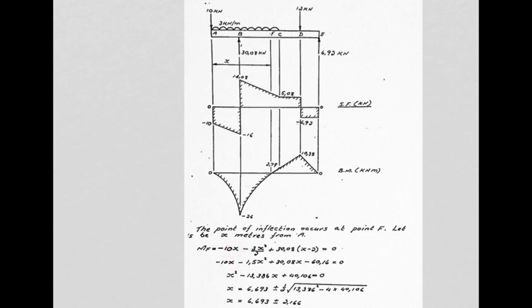And then we have minus 3x squared over 2. Well, that is 3 per meter times x over 2, remember, because x over 2 would be the distance to the midspan, and that ends up as 3x squared over 2 plus 30.08 times x minus 2.